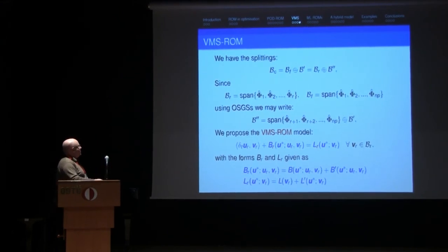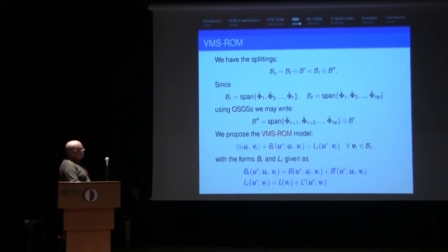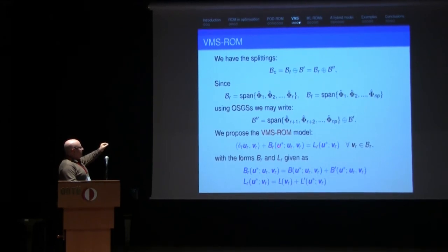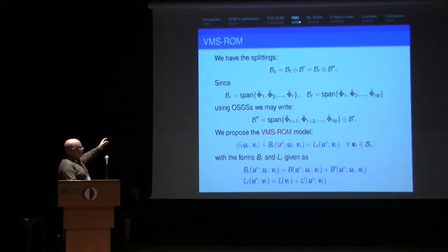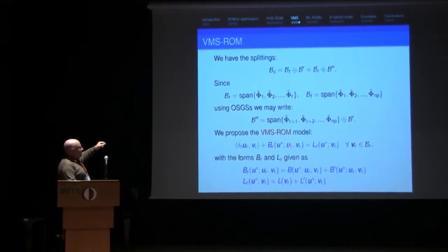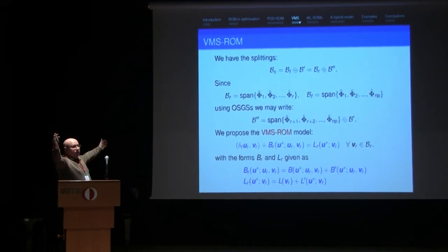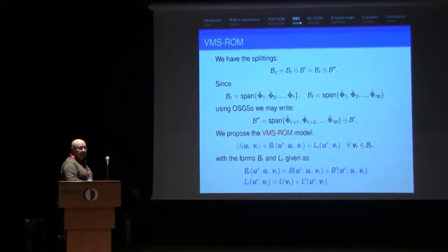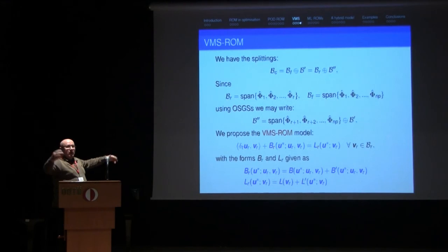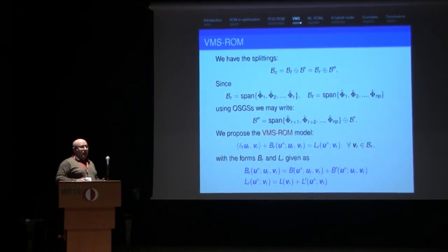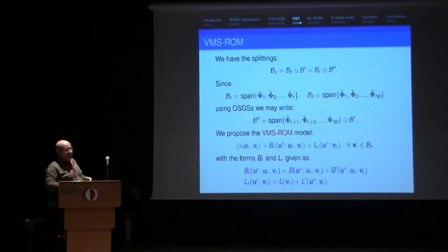Let me explain the idea. How do you have to evaluate this nonlinearity? You have the reduced solution, fine. But imagine you use a fixed point method, the Picard scheme. You have to use U of the previous iteration. So to evaluate this, you take the reduced order solution, you expand it to the full order space, then you construct the nonlinear term, and then you solve the reduced system. But that expansion to the full order space increases the cost enormously. What those hyperreduction techniques do is try to reduce the cost of evaluating nonlinear terms. But that's something about which I haven't talked.